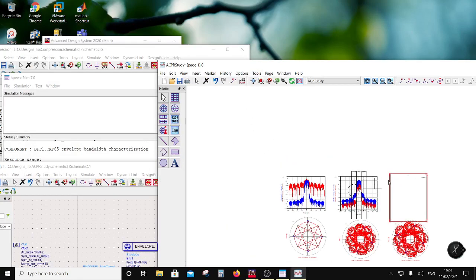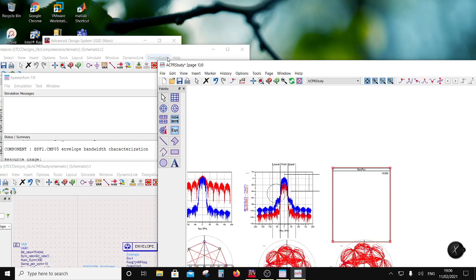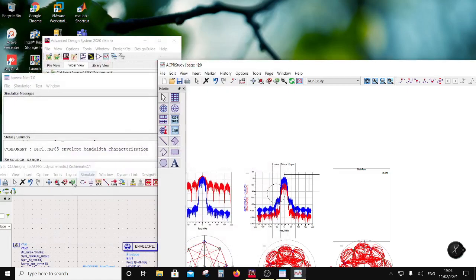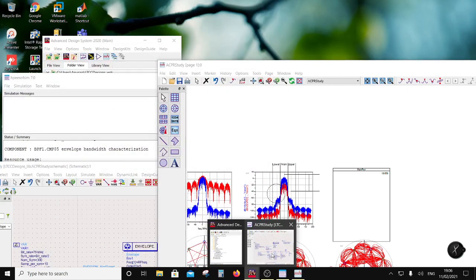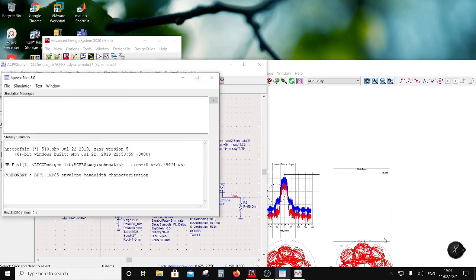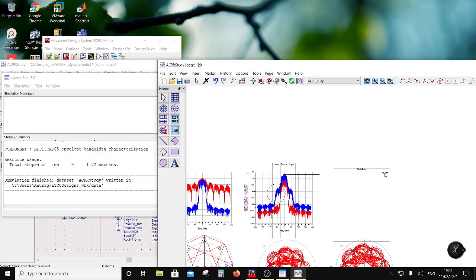So I'm putting in 0, I'm getting 18.6 out. Then I'm putting in 10. Okay, so I'm putting in here 10. So I have a gain of 18.6, right? So if I put here 10, then I have 28.6, but it is 0.6 dB compressed, right? So that's around 28.065, right? So now this is one power.